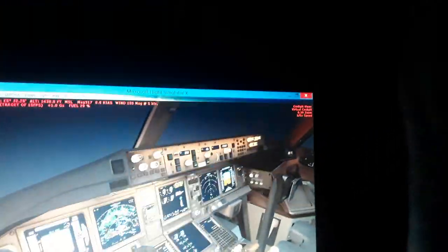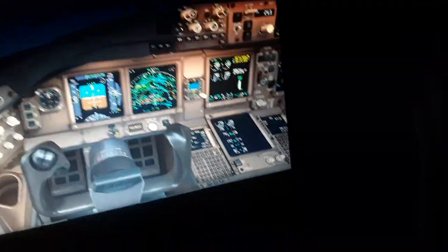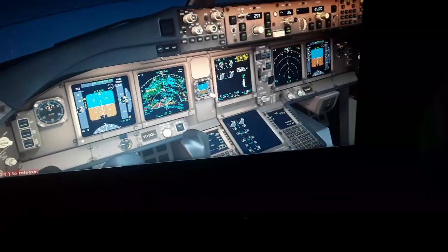I will come now to other data of the aircraft and other things like the flight controls. I will show you how to use the flight controls for controlling the aircraft in flight. I will show you how to use this side stick for controlling the flight controls, like the horizontal elevator, the vertical rudder using the rudder pedals, the elevator using the control column, and the spoilers using the control wheel, for having directional control and stability in flight, and also use the horizontal stabilizer and the thrust lever.